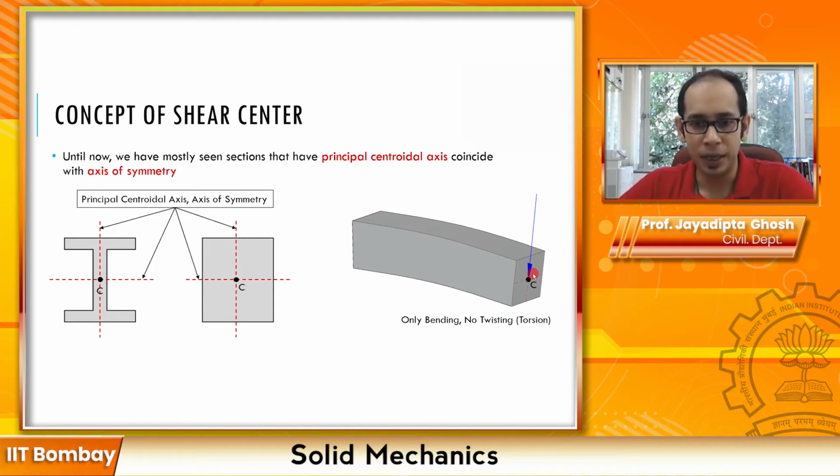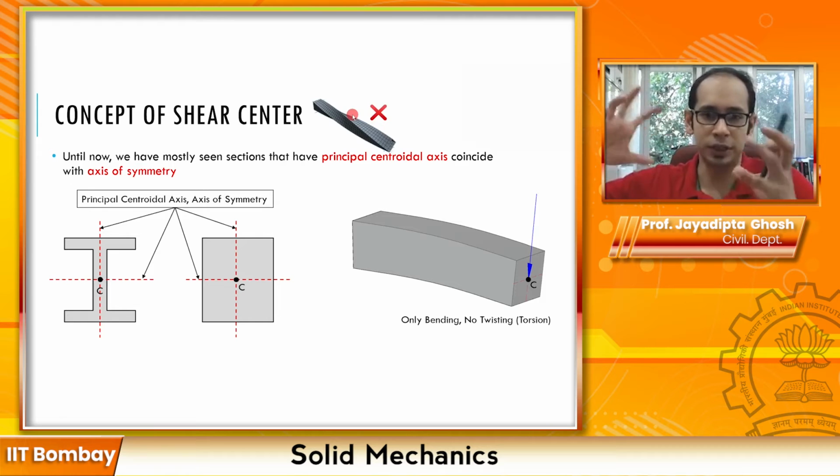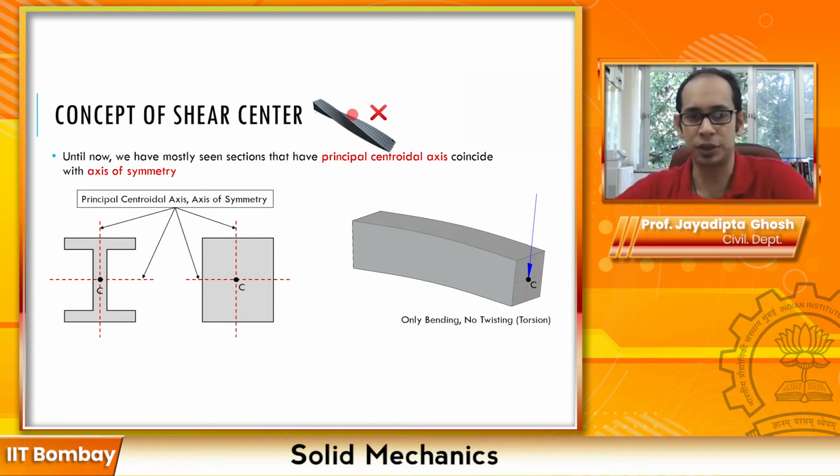When you are applying a load P at the center, you will see that these kinds of beams, both this one and this one, if you have an I section also, it bends and there is no twisting, right? So these beams do not undergo this warping kind of a thing, this twisting, this torsion, internal torsion doesn't occur, and this is also pretty intuitive to understand.